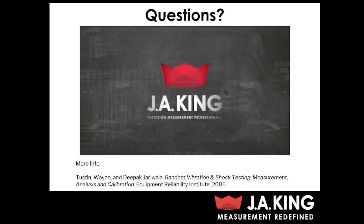And then also the duration of time that these parts are exposed per day. Typically for automotive testing, we'll expose parts to that noonday irradiance for 16 and a half hours a day, which of course is a much longer period of time than they'll actually get exposed to per day in the field. So this can help you accelerate testing as well.